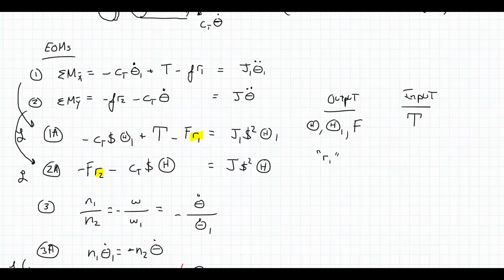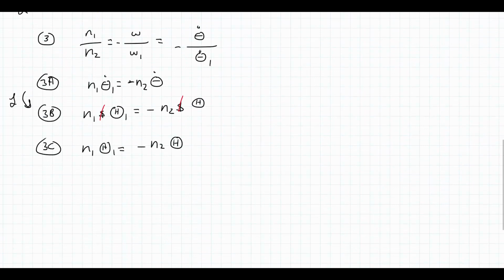But that means I do need one more equation now. But all it is the relationship for proper meshing or fully meshed gears, that the ratio of N1 to N2 equals the ratio of R1 to R2. And that will actually be a fourth equation that will be able to eliminate R1 and R2 and replace it with N1 and N2, which once again were given to us.